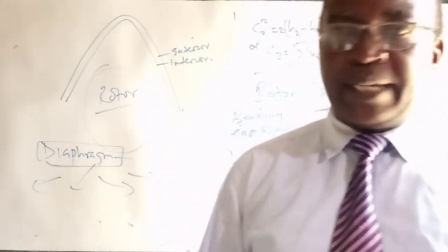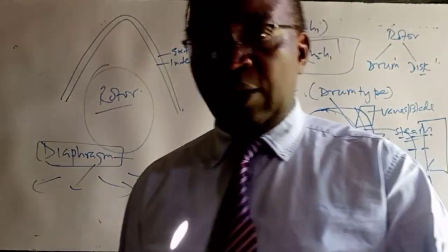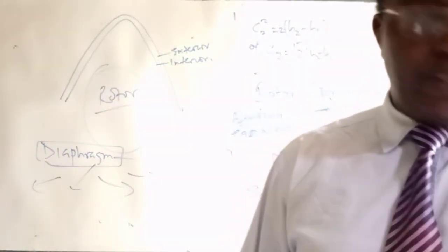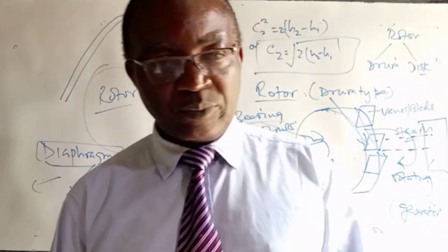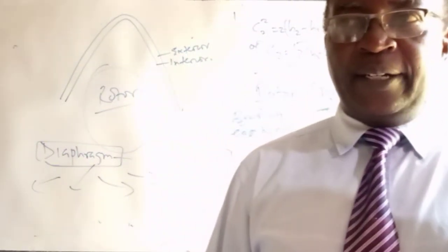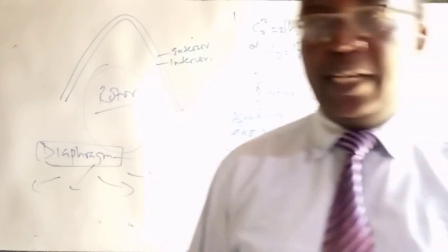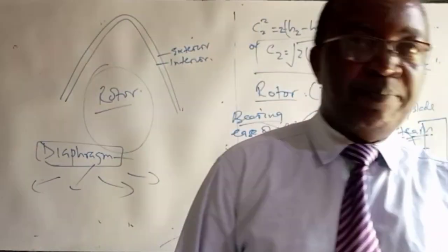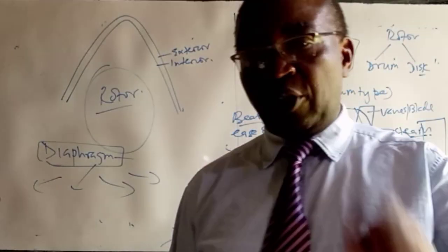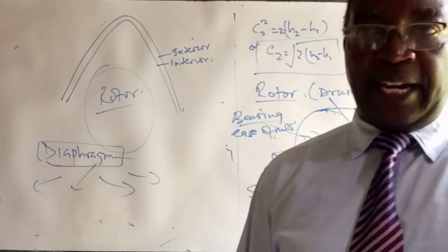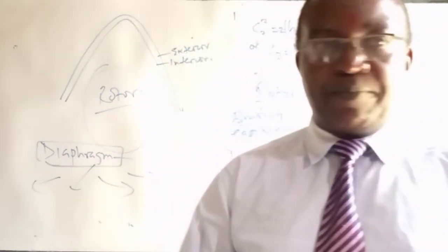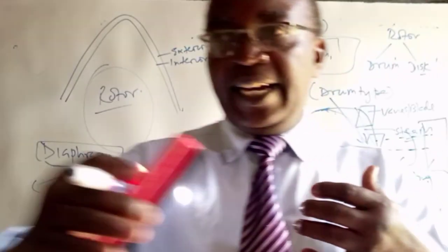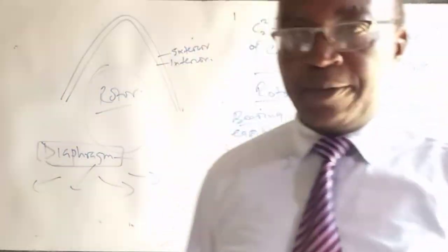And the nozzle, a very important unit there, because it's the one which enhances the velocity of the steam. And you have seen what happens in terms of the enthalpy change. And remember, enthalpy is energy content. When we talk of the change in enthalpy under constant pressure, enthalpy is heat transfer at constant pressure. So it is very, very important. That is related to the velocity, as we have seen in that particular equation.